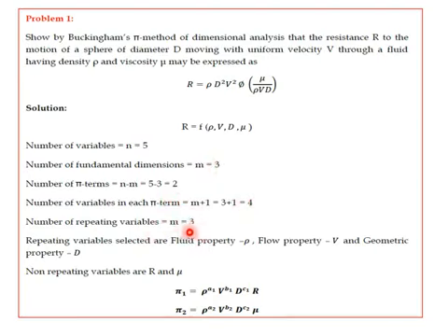One has to be a fluid property, so we take rho. Another has to be a flow property, we take v. Another has to be a geometric property, so it is d. So there are 2 pi terms now. How is it written? These rho, v, d are the repeating variables, and they get repeated in each of the pi terms. As far as possible, the other term has to be the dependent variable. So what is remaining? Only mu is remaining, so mu comes here as a non-repeating variable.